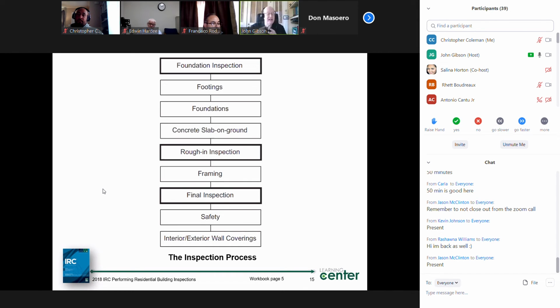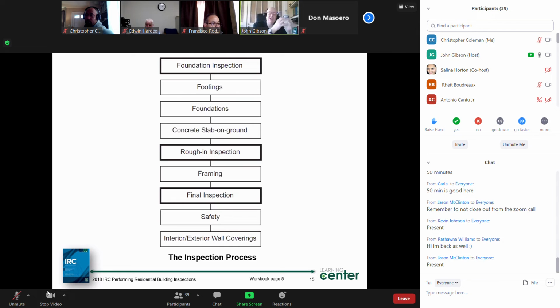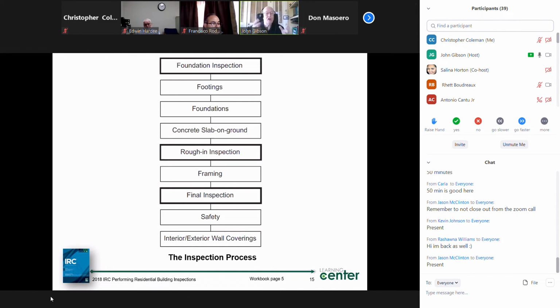And then finally, we have what's called final inspections, which pick up this idea of the things which transcend just a rough-in inspection, but also deal with an element in its final form. Let's look at a stair, for example. A stair component, which is typically part of my means of egress in a residential structure, it would be roughed in and my opening would be checked.